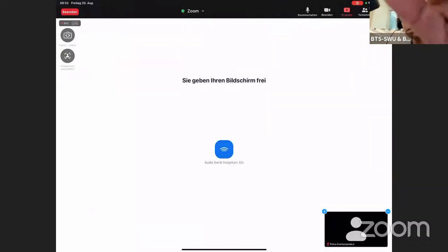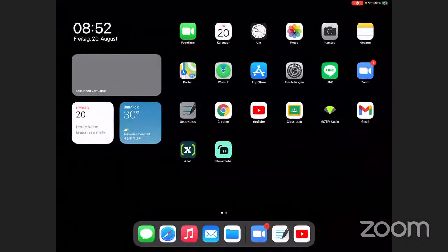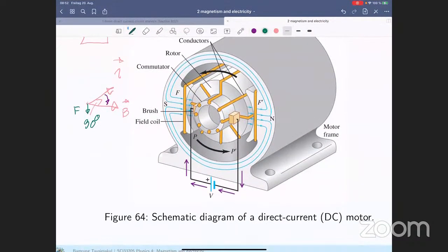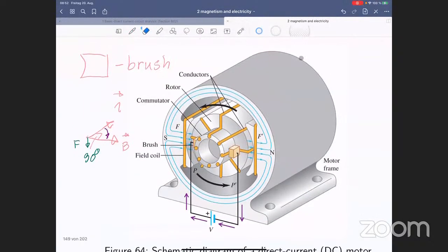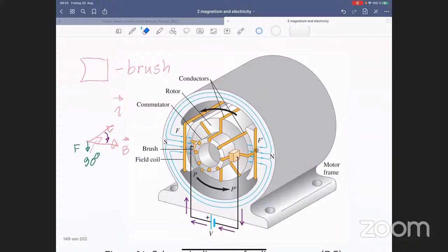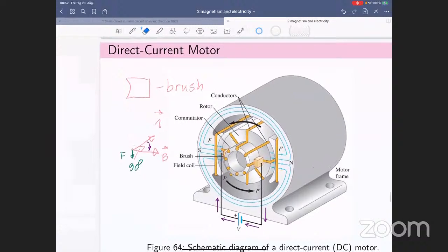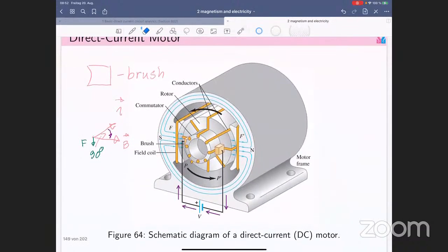Yeah, that's what's going on. On this side you see that the current flows from the back, the rear part of the motor, and then it goes this way, right? On the right side you get vector L like this, and vector B is going to be this way, right? But this angle is 90 degrees, right?